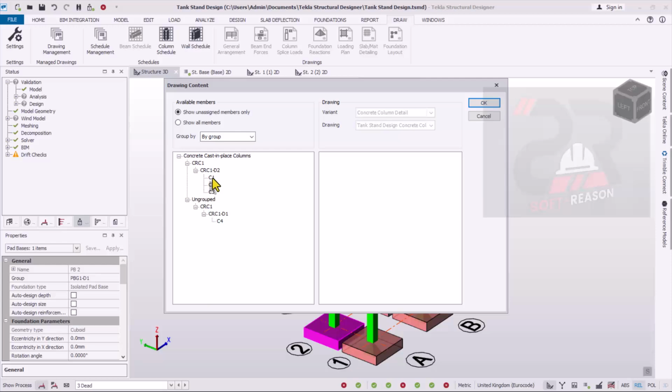and then these are all the columns. Okay, some of the columns are grouped, some are not grouped. I want to advise bring all and produce all the drawings, because not all the columns are similar. Some of the columns, the reinforcement may be changed, but the sections are the same, so they cannot be grouped as the same column. All right, so I've put them in this panel.